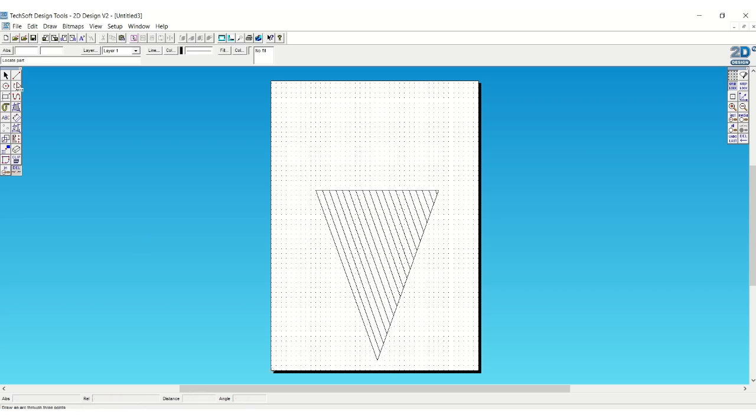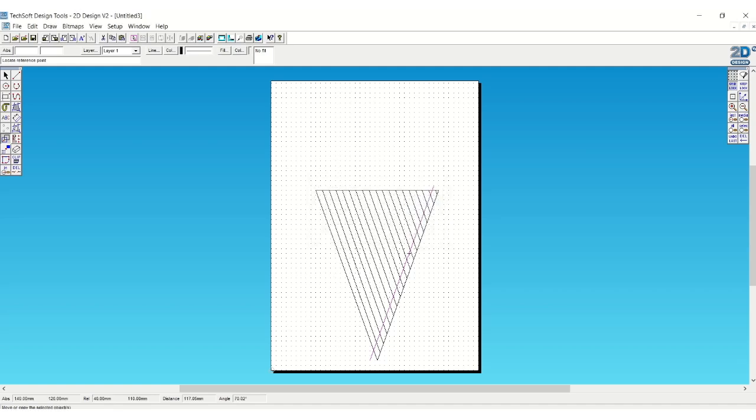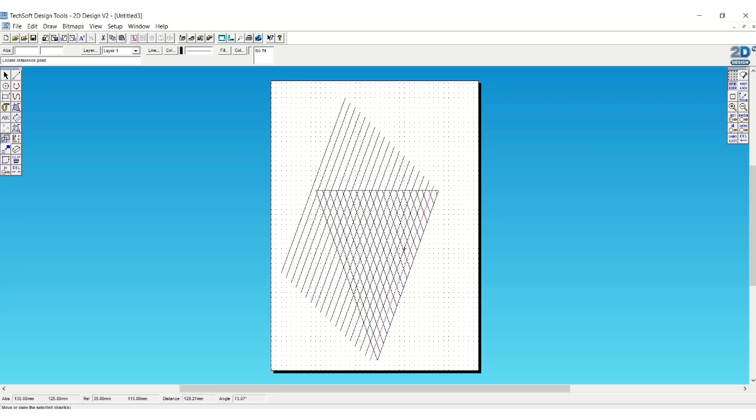Okay, so now my cone is stripy, but I want kind of a grid pattern to make it look like a wafer. So I'm going to go on the other side and draw another line and just repeat the process. I got exactly the same on here. So the repeat, select my line, use a repeat tool. So click that on here, same number of times, click OK. And just pull that little bit, kind of the distance on them, and I want them repeated.